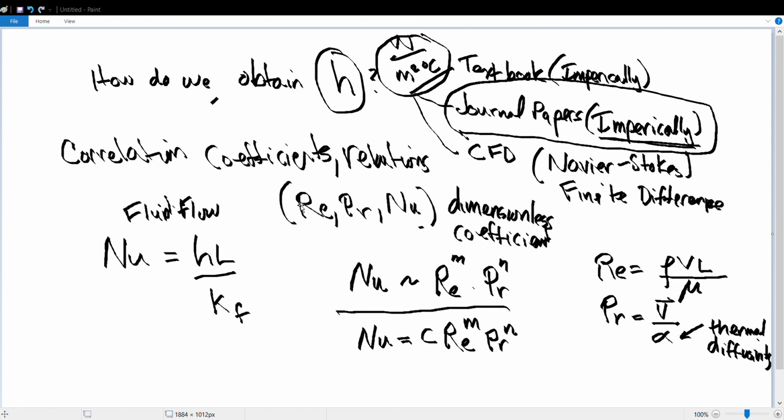Depending on if you have inline pins or tubes, one next to the other, or staggered, and depending on the Reynolds number, you will have different Nusselt equations. Now this one has the Pr_s. If you look down here, Pr_s is the Prandtl number evaluated at some average temperature, for example.